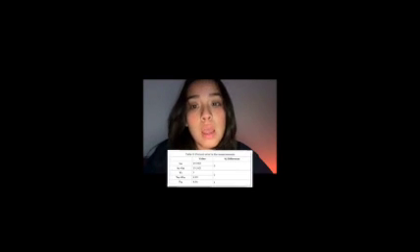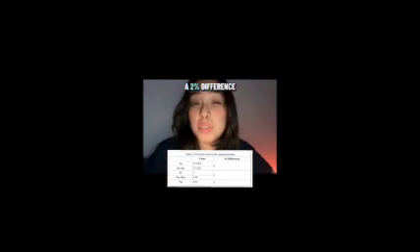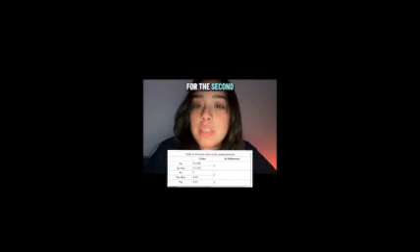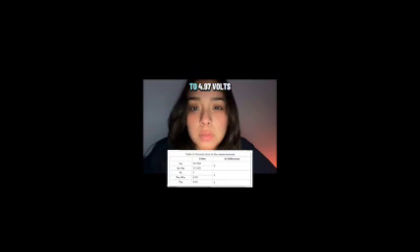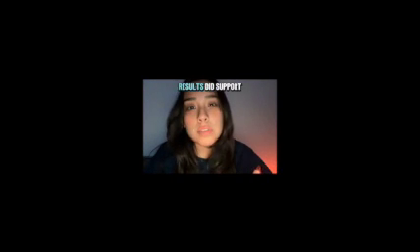Next, using Kirchhoff's loop rule, the total voltage from the source should equal the sum of all voltage drops. For the first loop, the source voltage of 7 volts should equal VR1 plus VR4. When we add those, we get about 6.99 volts, which is about a 2% difference. For the second loop, VR1 should equal VR2 plus VR3. Those add up to 4.97 volts, while VR1 was 4.96, only about a 1% difference. So overall, our results did support both of Kirchhoff's rules with very small percent errors.